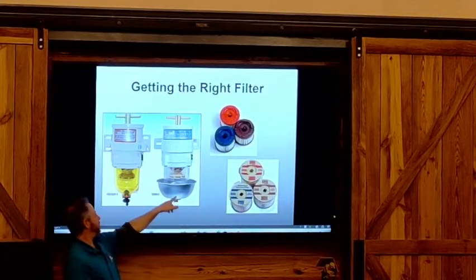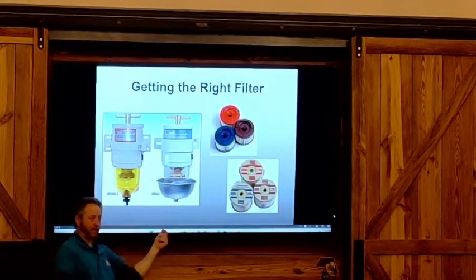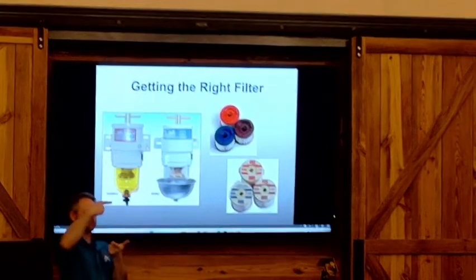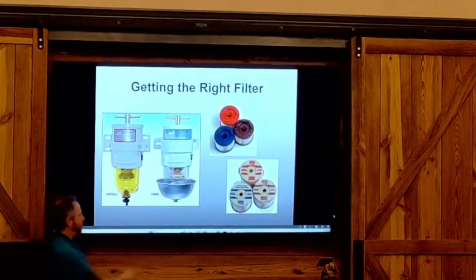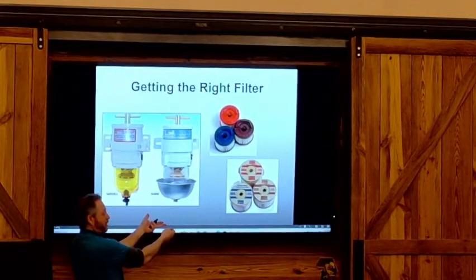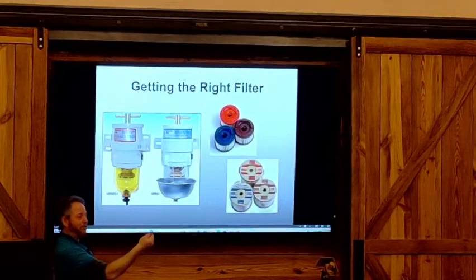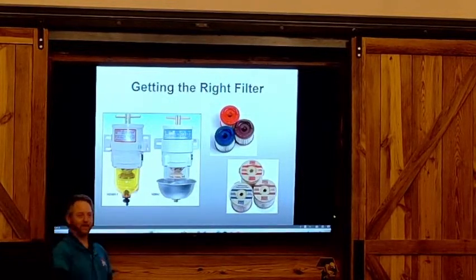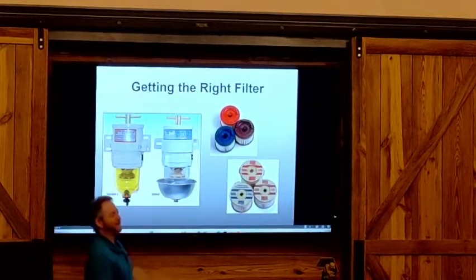And then when you go to drain any water or sediment out of the bottom of the bowl, you've got this hex plug that you pull out to drain the water out. But you don't want to drain the entire thing, there's no reason to drain all the good fuel that's in there. You just want to drain the water and the sediment out. So you pull the plug out, and you've got a pan underneath it, and once it turns to nice clean fuel, you go to put the plug back in, and you're trying to get it in there before all of it runs out, and then you go boop, it pops out of your hand, so then you put your finger in the hole and get to it.